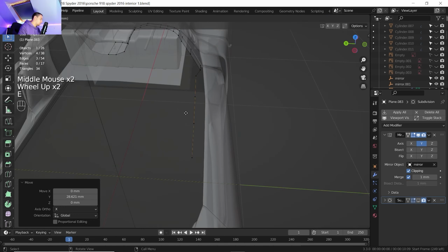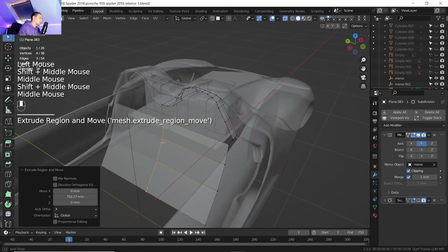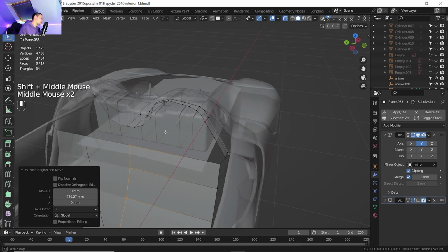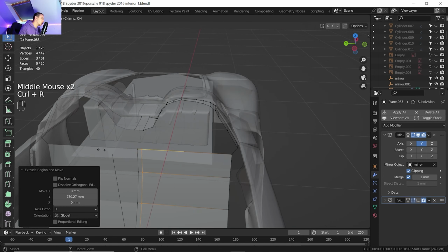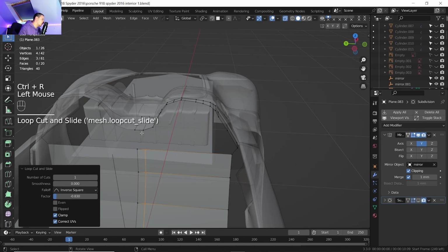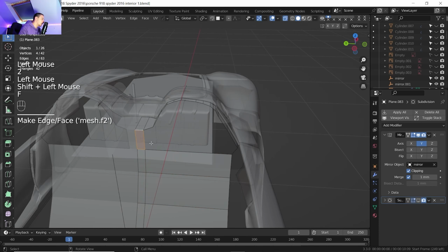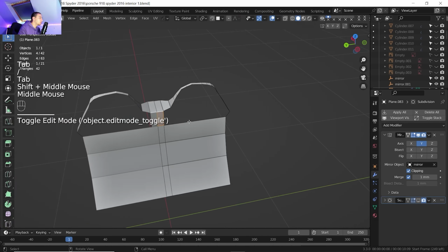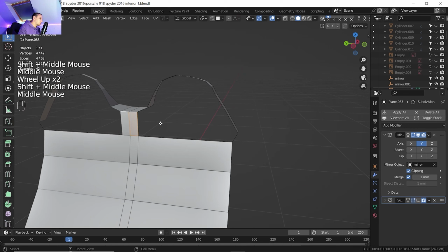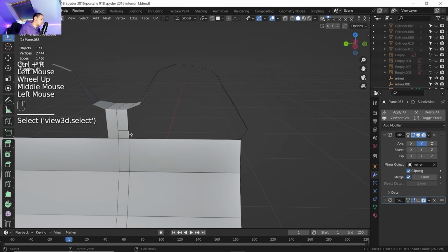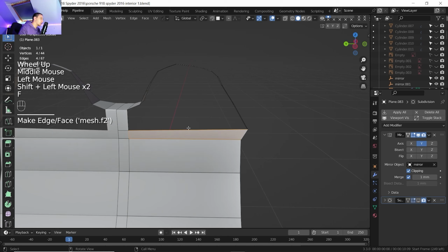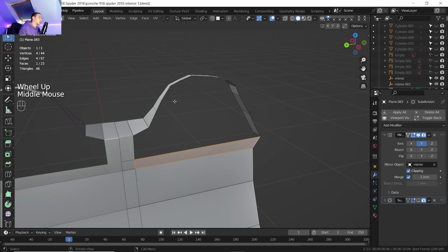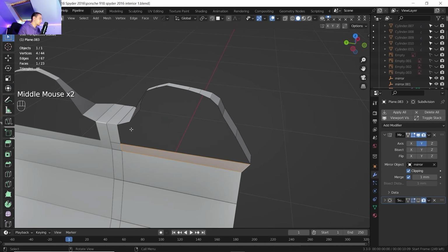Now I can do the other things like extruding on Y like this. And from here I'm just needing to fill out the spaces. So first off, let me just put one edge loop around here, F for the faces. I don't need to see through anymore. Going into local view. Now we are gonna need to create a lot of edge loops. First off, let me just solve also this area here, because I need also an edge loop around this part. Then anything else is just gonna have its face.